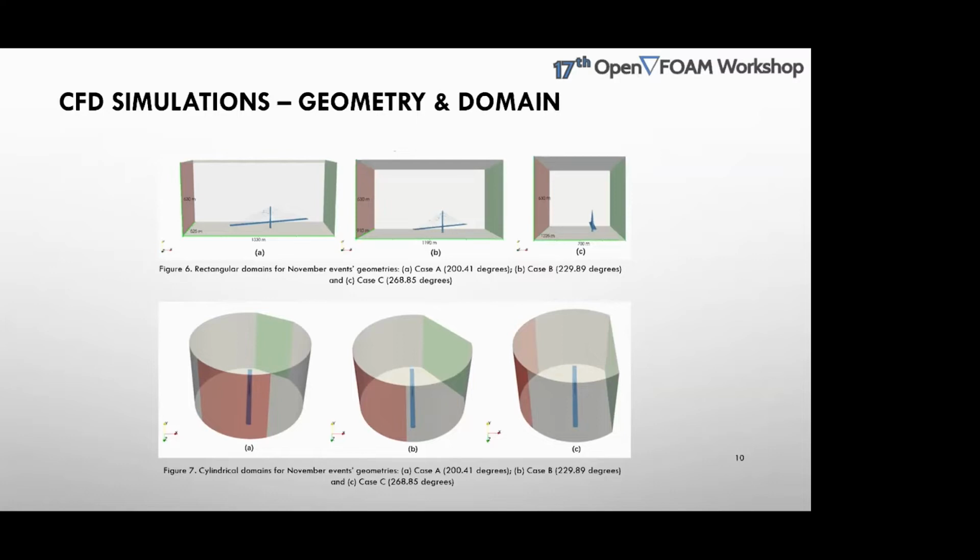So for the rectangular domain, normally there are 2 ways to deal with these yaw angle studies. The first one is, as I showed here, to rotate the model or to rotate the domain. But changing the yaw angle of a model like this is quite likely to face issues such as unsuitable domain size or unsuitable refinement region size. And you may also have to change the desired data point collection locations. So we have to recreate everything again, which is quite troublesome.